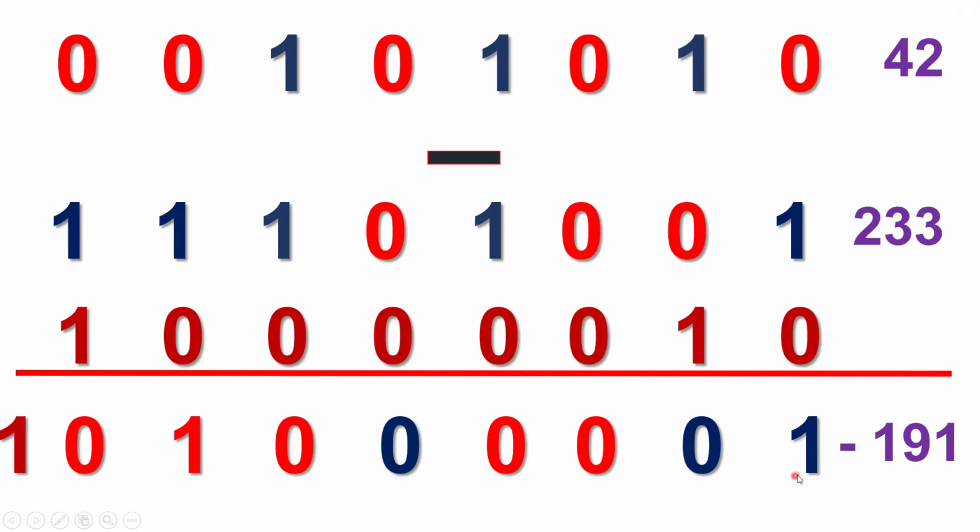So you see that to represent 191, we need a total of 9 bits in the difference output. So this 1 at the MSB is indicating a sign, and the remaining 8 bits indicating the magnitude of 191. So this is a signed binary number which required us 9 bits to represent that. Okay. So that is how we did that.